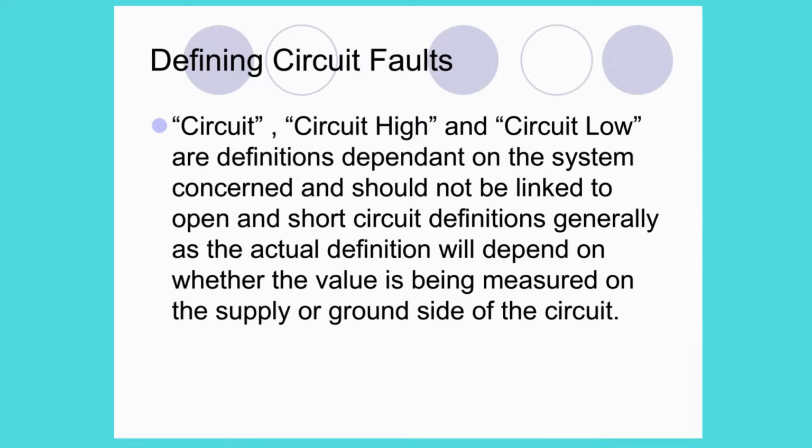Circuit, circuit high, and circuit low are definitions dependent on the system concerned, and should not be linked to open and short circuit definitions generally, as the actual definition will depend on whether the value is being measured on the supply or the ground side of the circuit.